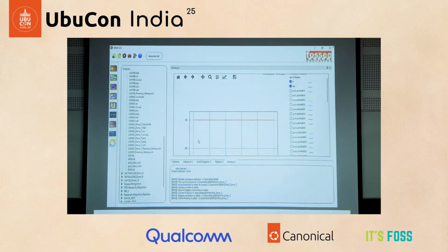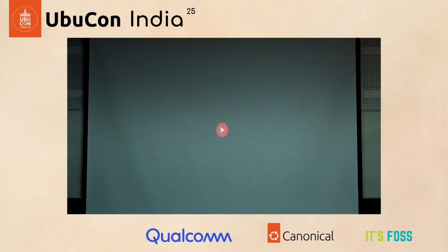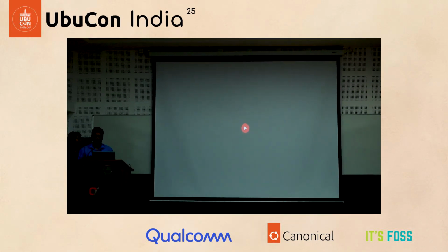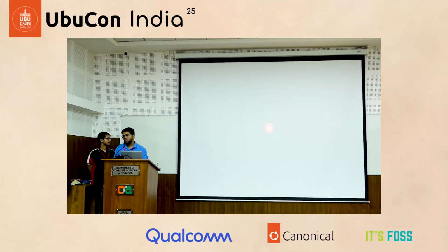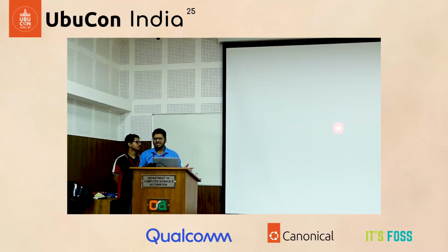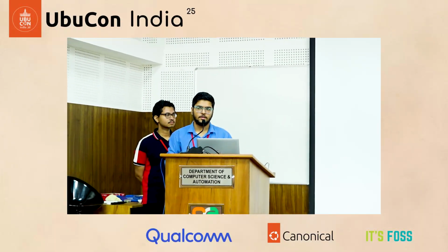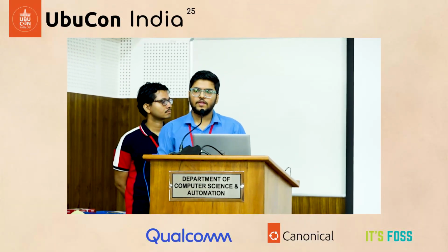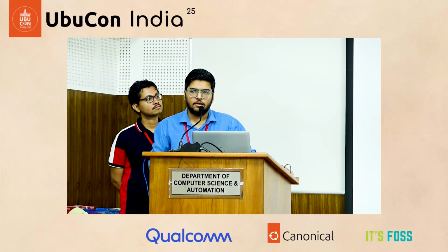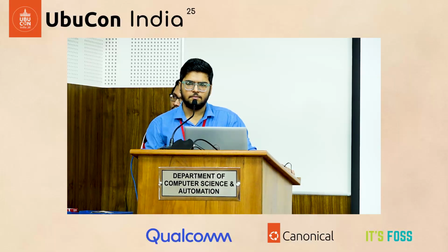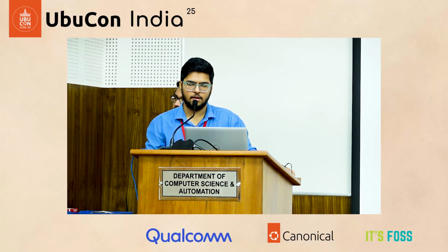So it's to showcase that you can create your own ICs or subcircuits from the transistor level, and you could design your own circuitry to get this simulated. What you can do is create a workspace, open that workspace, create one project. Within the project, create one schematic. In that schematic, you'll be adding all of the circuit. If you're following any circuit, you could add that.